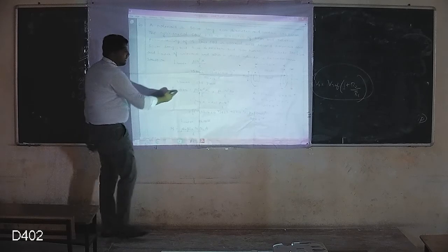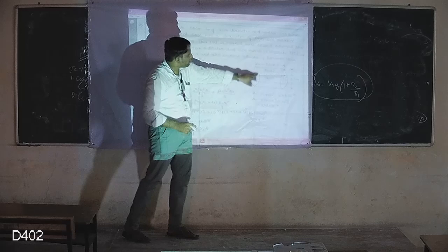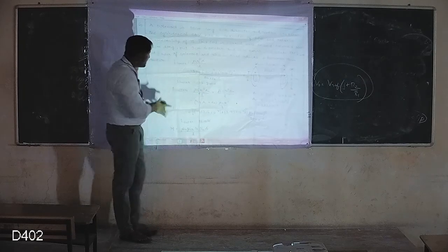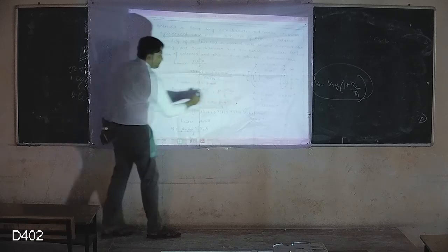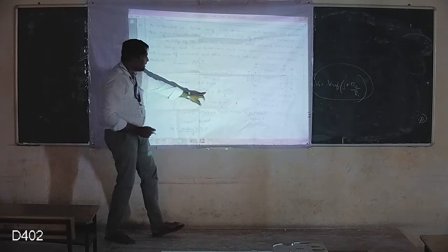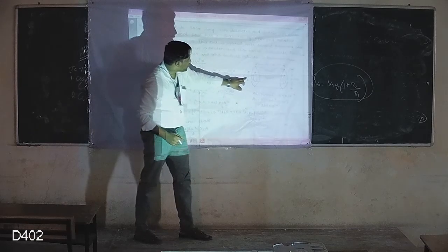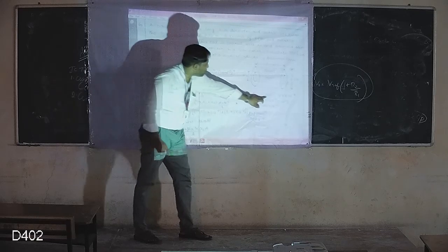Second answer, L outer. If I take the second solenoid, the first solenoid is also coaxially within it, so we have to take the combined effect. Therefore, L outer is equal to inner plus outer. For inner, A is equal to pi times the inner radius square. What is the inner radius? 2 centimeter is the diameter, so the radius is 1 centimeter, which is 0.01.